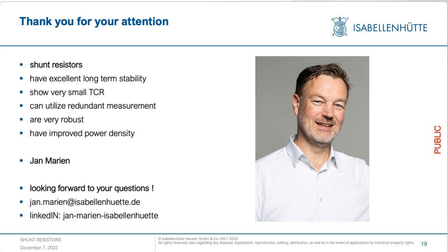Are there any concerns with mechanical stress in the shunt when the mounting surfaces are not flush with each other? So far we have no experience with mechanical stress in the shunt, as long as it is a proper process in the application. For SMD shunts, the welding process and also the material of the PCB board is important, but this is rather standard in the industry.